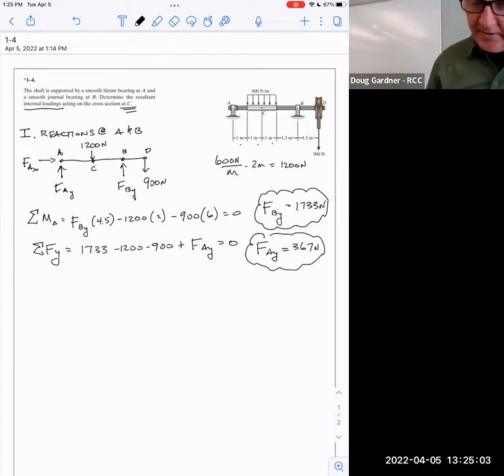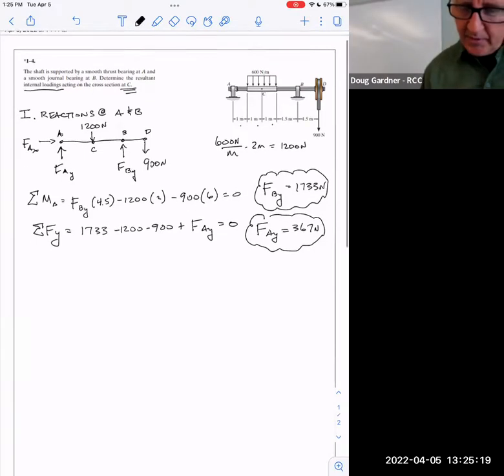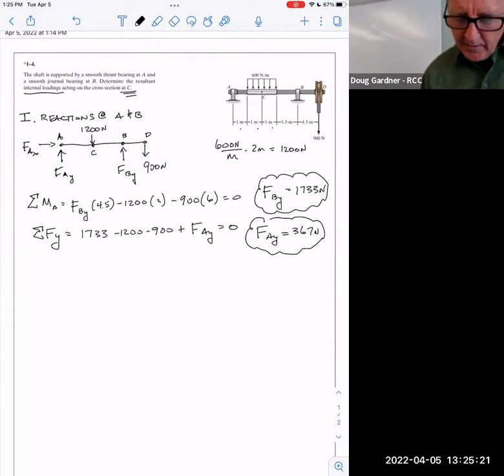And so fortunately, instead of saying find out everywhere, which, does it make sense? You'd actually need to know that. We don't want that rod to break. So we really need to find out the worst place for all these things to happen. That's where we really need free body or shear moment diagrams, but they're taking the pedal off a little bit and just picking a spot. So let's do now these internal loadings.